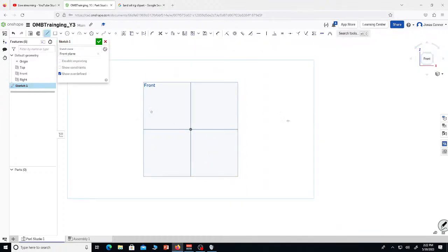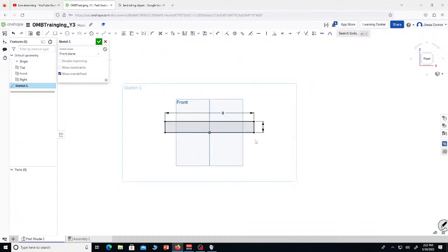So we'll just say like a line here. It's like one inch, 8 inches. Now typically you want to have your part defined off the center, but we're not going to do that because we're rebels. What we'll instead do is just have a square. We're going to make this perpendicular. And then we're going to make the center of this, the midpoint, coincide, and where's midpoint? Midpoint. Boom, boom. Okay, now it's kind of attached.